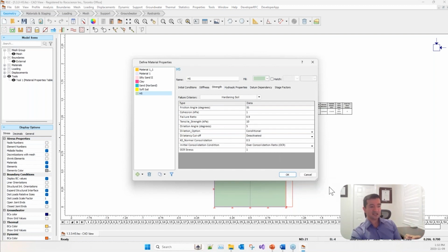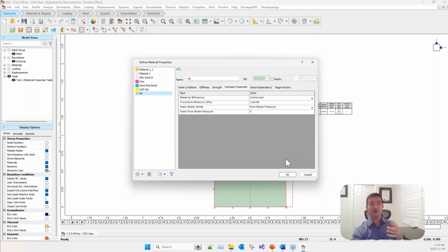But in most cases that I will show here, I was going to simulate behavior that we see from clay materials. Even the example that I will present later is going to be clay material. So in all of them, I'm using dilation angle equal to 0. If you have dilation angle, as you saw here, this formulation that we have for undrained is able to handle that. There's no problem there. But when you have dilation for undrained material, then you have the generation of negative excess pore water pressure, and the material can handle a higher level of shear stress. So it's just the material properties. Yeah.